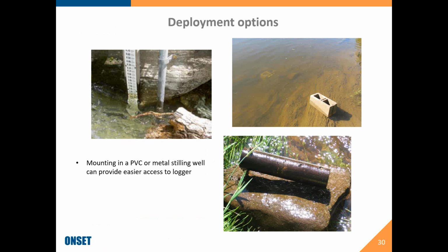If you're deploying loggers with direct readout cables like the MX2001s that I showed you, in most cases you'd need to put them in a stilling well like this so that the top unit with the Bluetooth communications is above the surface so that it can transmit wirelessly for readout.